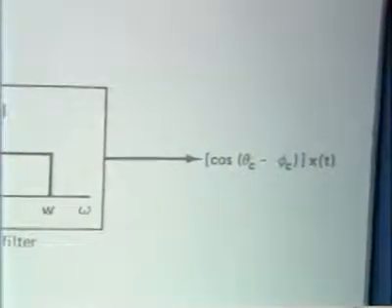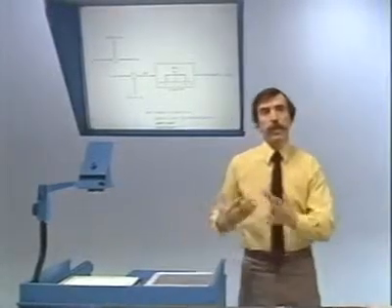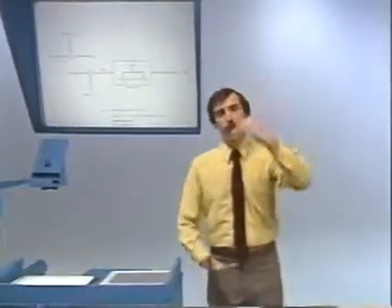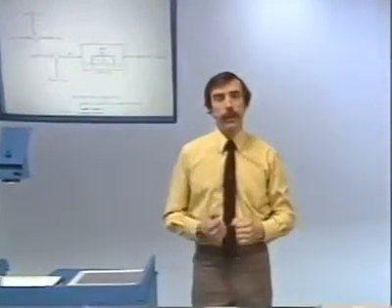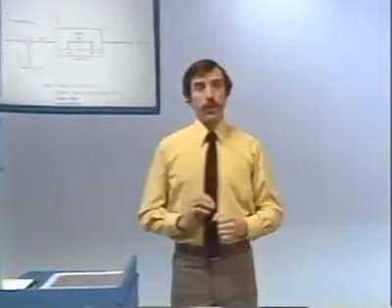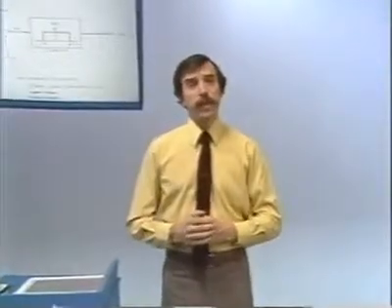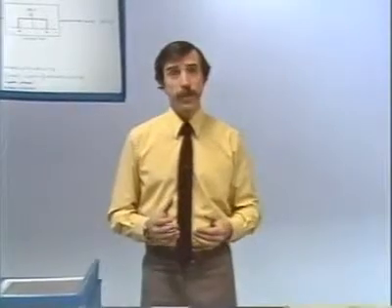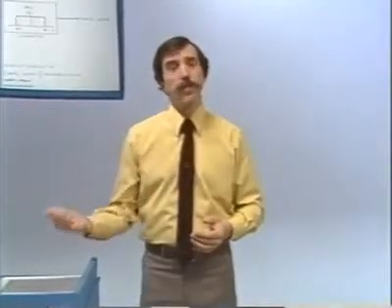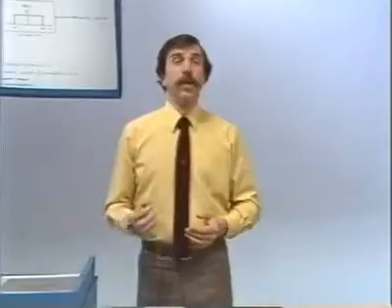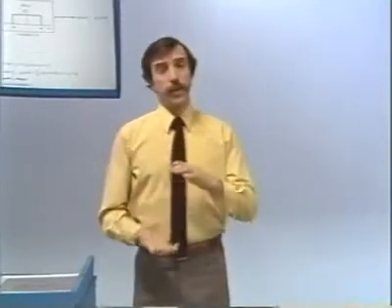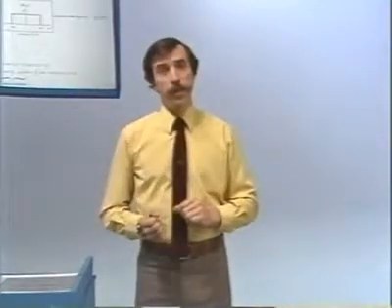Now, one could ask, okay, what's the big deal about a scale factor? If it's too small, we'll make it big. If it's too big, we'll make it small. But there are several points. One is, notice, for example, that if the phase difference between the modulator and demodulator is 90 degrees, then in fact the output of the demodulator is 0. Or if it isn't quite 90 degrees, the amplitude might be small, and the implication would be that if there's other noise that gets injected in the system, the signal-to-noise ratio is very low.